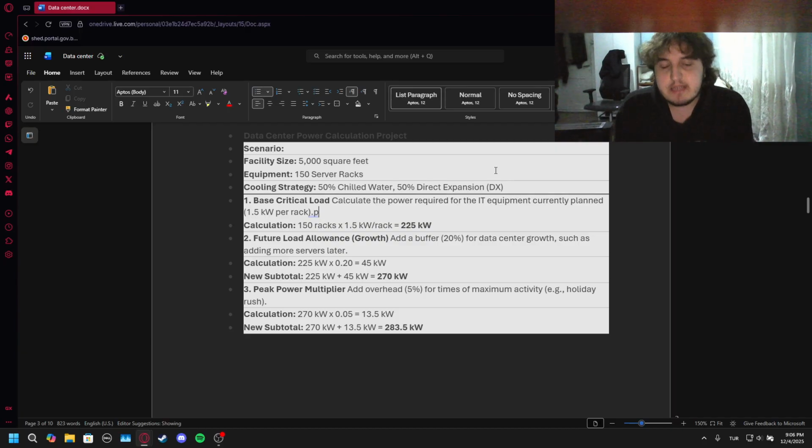Like I said, the 20% is all of that. Calculation: 225 multiplied by 0.2, 45 kilowatts. You added that and you get 270 kilowatts.